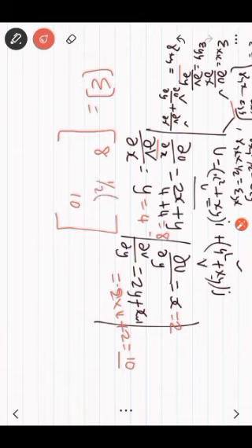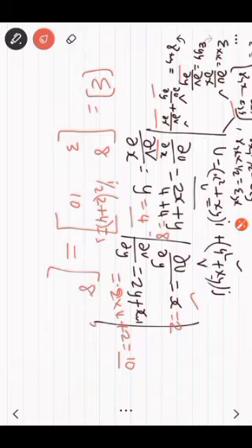Half of gamma xy. Gamma xy is, we have to add dou u by dou y, that is 2, plus dou v by dou x, that is 4. So it is 6 over 2, so this is equal to 3. So you have the strain tensor as 8, 3, 3, 10. So this is the strain tensor.